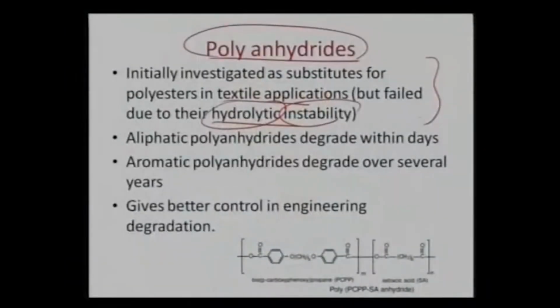But eventually that triggered the development of these polyanhydrides as bioabsorbable or biodegradable materials. And again we can see that the polyanhydrides are very specific in that the aliphatic polyanhydrides can degrade within days, whereas the aromatic polyanhydrides degrade over several years. So we can see that we have a certain window available with us, that aliphatic polyanhydrides will degrade within a couple of days, whereas the aromatic polyanhydrides will degrade over several years.